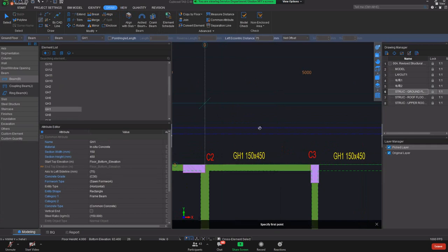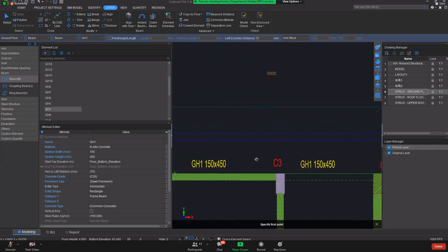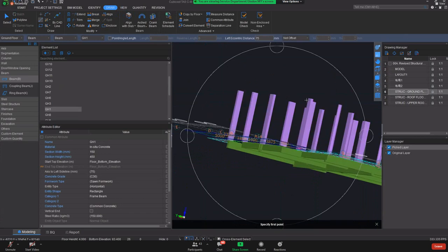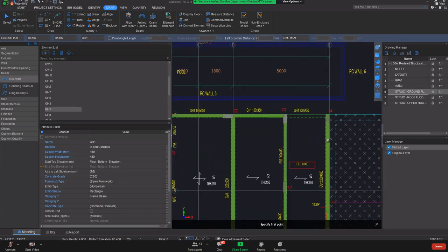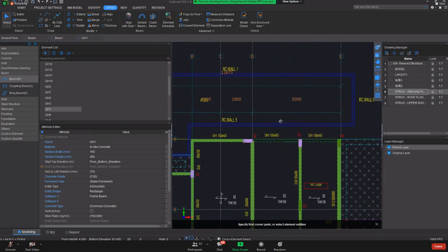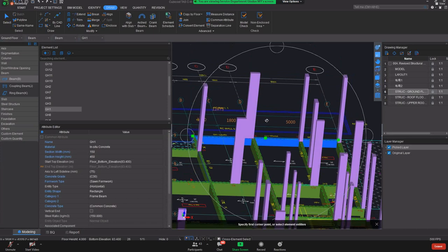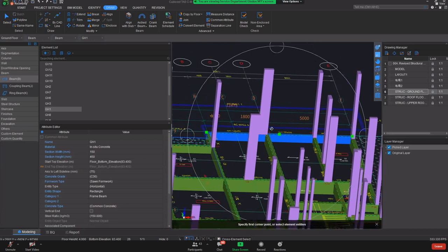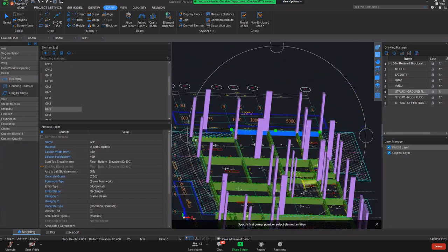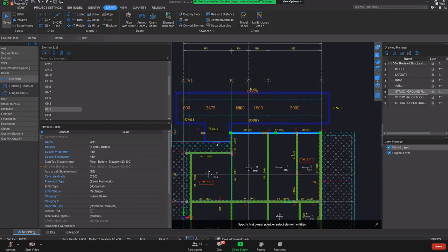So in fact, you do not need to do so. Okay, you can just simply penetrate through the whole beam, because the quantity will be as per the SMM. Okay, vertical element takes precedence. Okay, then it will automatically deduct. Okay, don't worry about that. Okay, you can just freely penetrate through the vertical element. Okay? In fact, the vertical element will take precedence.